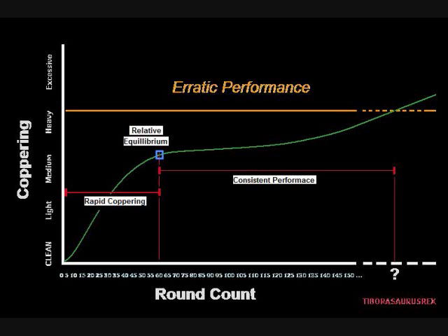There is a certain point as you're building up copper in your bore to where it'll level off, and it will continue to build slowly over time. You also still have these erosion mechanisms we talked about earlier taking place. All these things are happening simultaneously, so it's not a real simple deal, and things do change anyway. But there is basically a certain point where it levels off, and that's the point you want to be at.